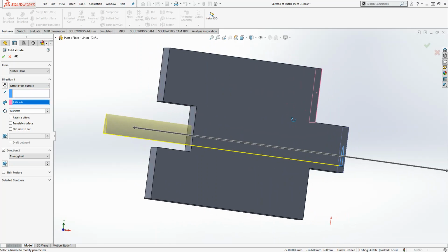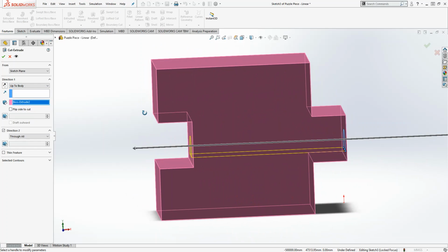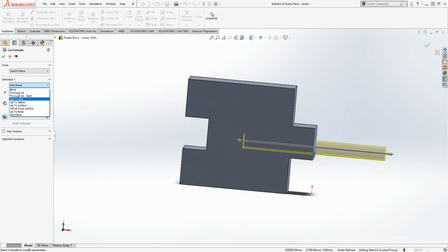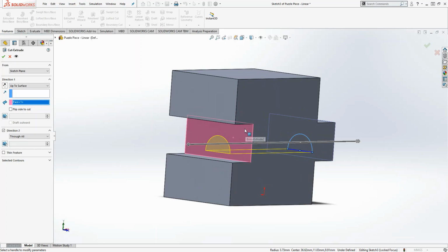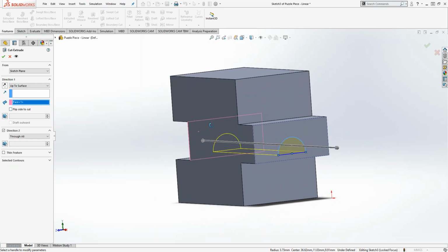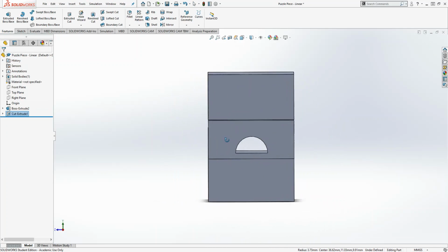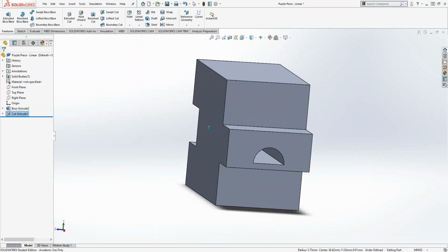Pretty good, honestly. But perhaps I want to make it more like an actual thing. I'll go a good solid 20 millimeters. So we have this thick-looking puzzle piece. As you can see, I have the original sketch pattern on the side here, outlined in blue, and then the extrusion goes out in a certain direction. You can also extrude multiple different sketches or shapes on a sketch all at one time by selecting the different contours. As you can see in red, that's the contour of my sketch.